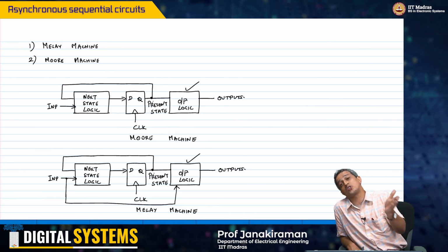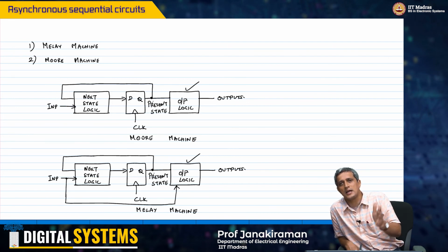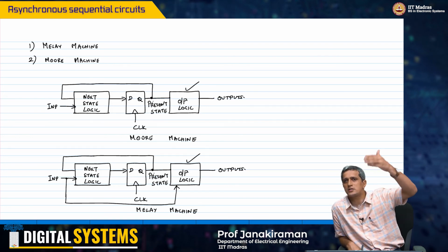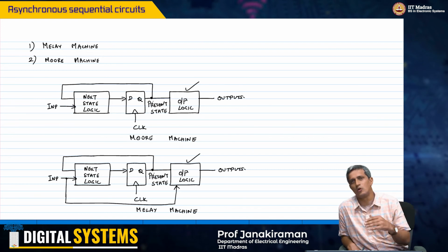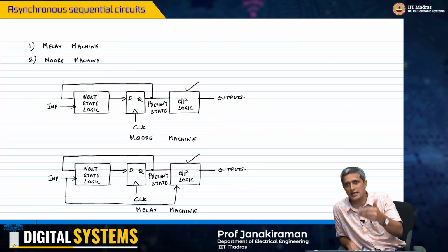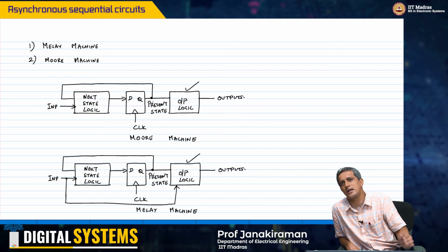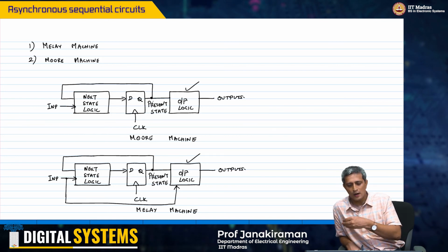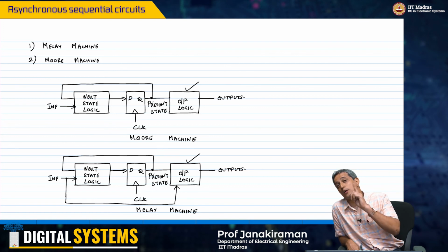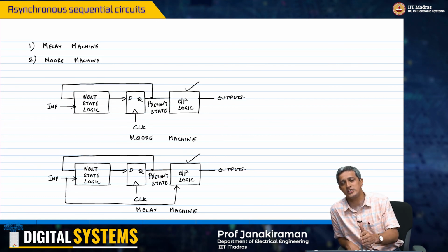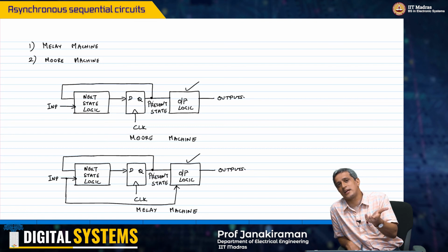But I could also simply take all the states and AND them with a reset signal, which is the input signal, and just cause the output state to go to 0, right? Now if you did it in the latter way, where you put an AND gate at the output of the flip flop and just AND it with the reset, that becomes a Mealy machine, because the reset now can control the output of this logic directly, which means that any time the reset changes, the change in reset can affect the output and the state automatically, right?